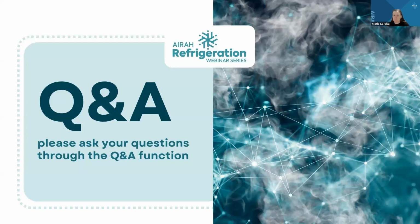Yeah. Yep, no problem. Next one here from Andrew is, why isn't the defrost cycle of cold rooms, so hot gas bypass defrost, not considered in the heat load calculation and only freezer rooms? Well, with chillers, we often use off-cycle defrost for that reason.